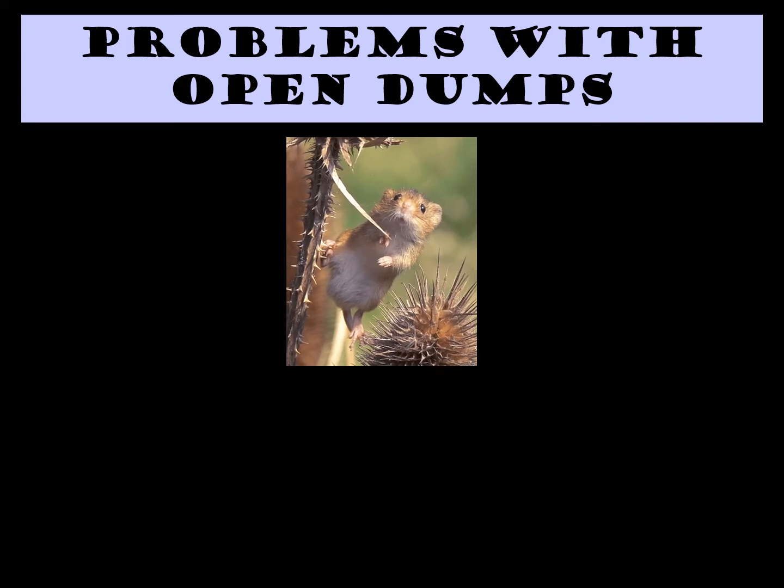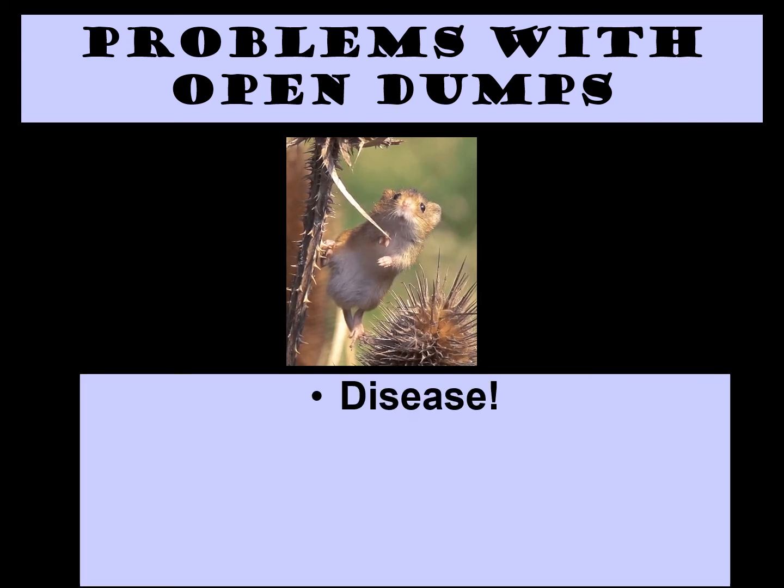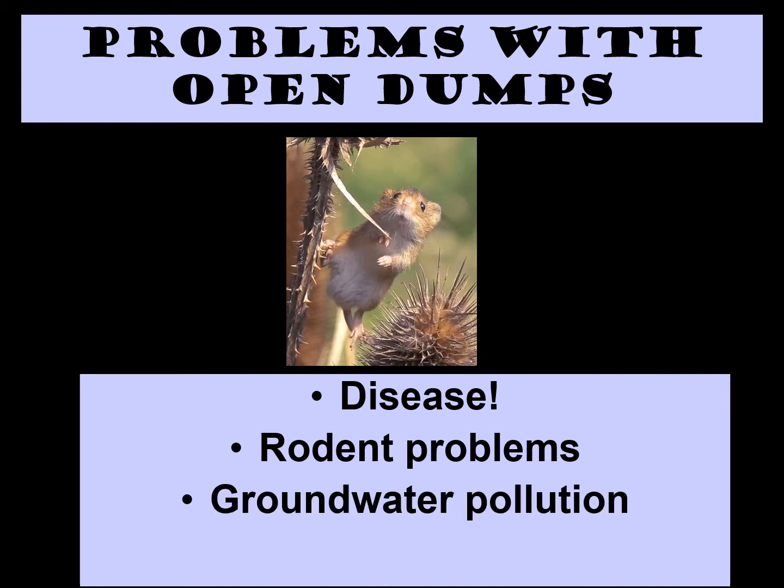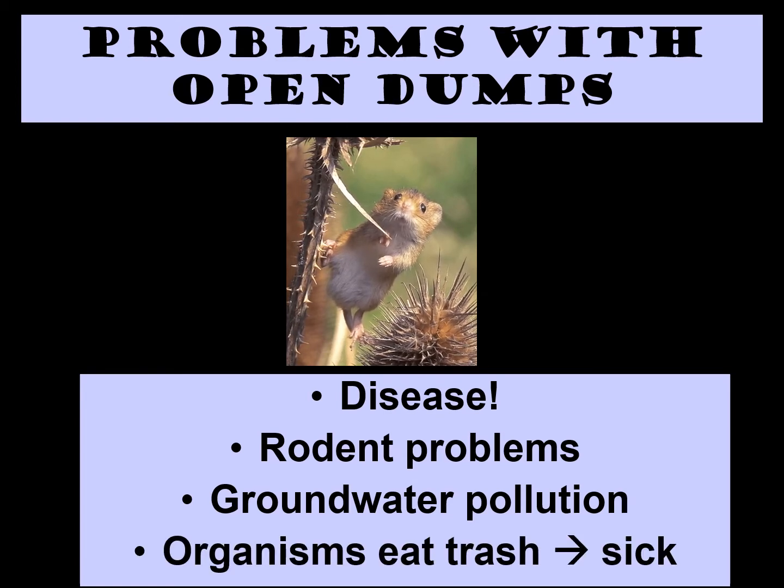Open dumps do pose a lot of problems. Number one, disease is pretty rampant at open dumps. You have a lot of bacteria and pathogens in that solid waste. Rodent problems are also an issue. They do tend to gravitate towards that solid waste. The solid waste also can decompose, and all of the leachate can get into the groundwater and cause groundwater pollution. And lastly, any native species that live in the area may eat the trash and become very sick.